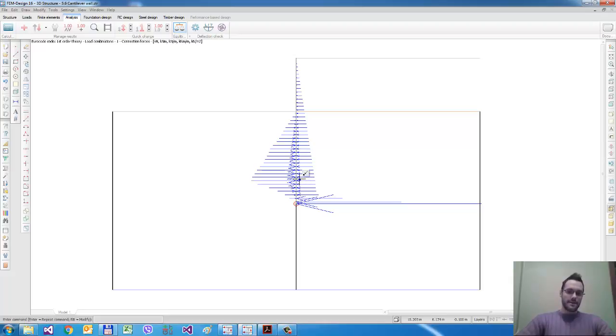And in this case there will not be just an active earth pressure here and a passive earth pressure here, then the result will be a mixed earth pressure. So somewhere here we'll have an active earth pressure, then here we'll have a passive one, and we have a change in this active and passive earth pressure distribution somewhere here according to this rotational point.